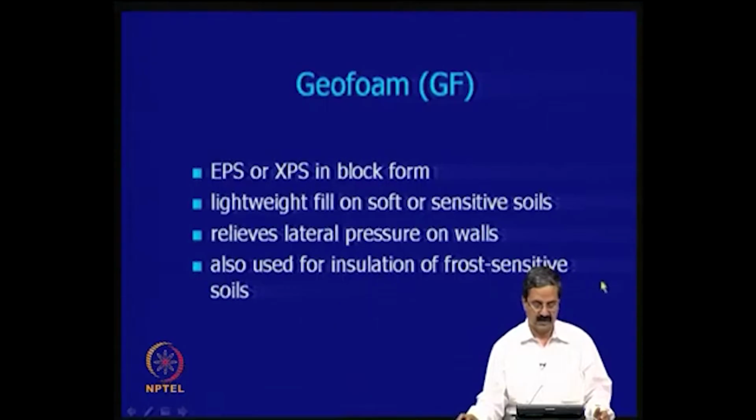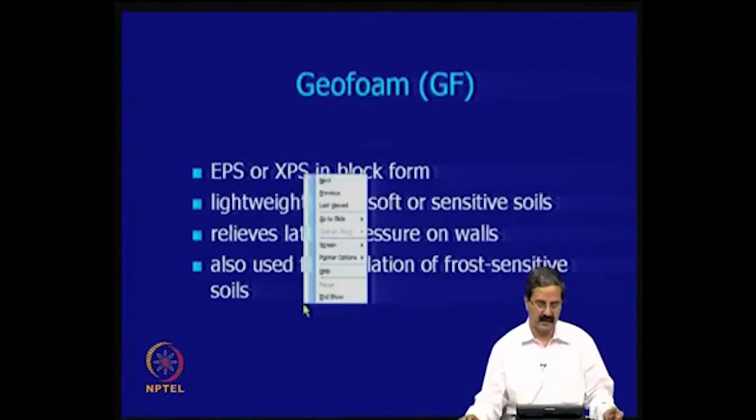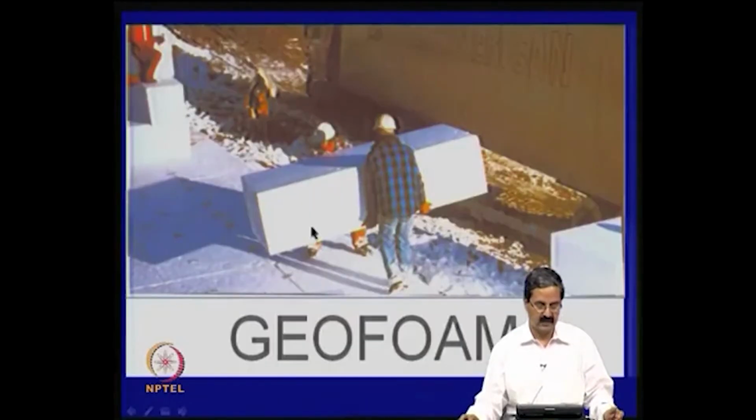It is also used for insulation of frost sensitive soils. Its compressibility is quite low, but at the same time it is easy to lift. Like you have seen, two people can carry it, and the advantage is that it can even be used for road applications. Many applications are there, we will see that.